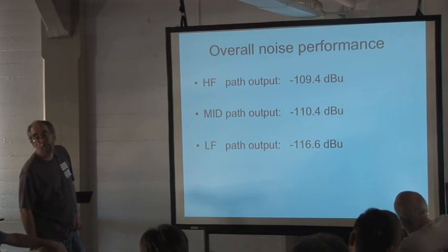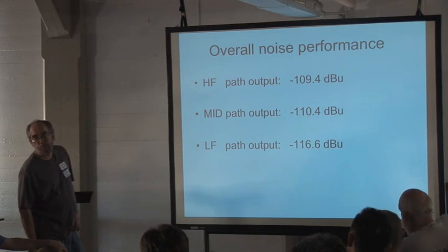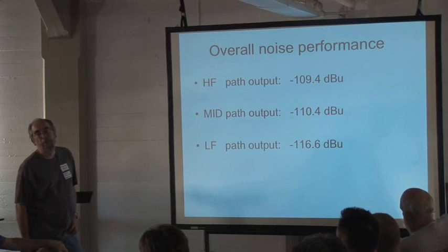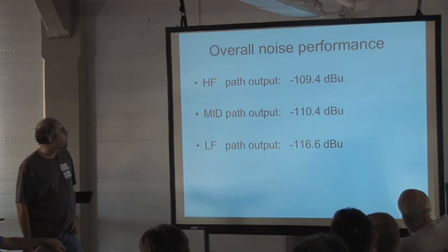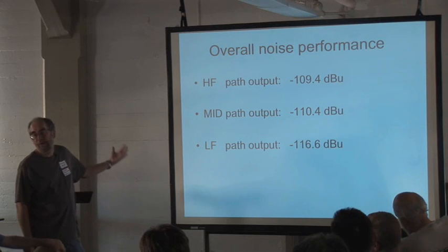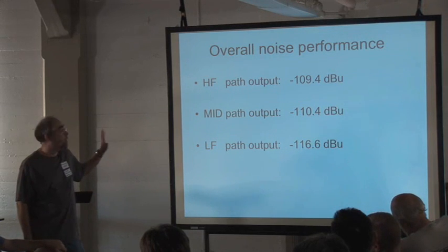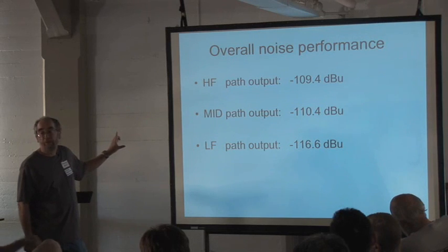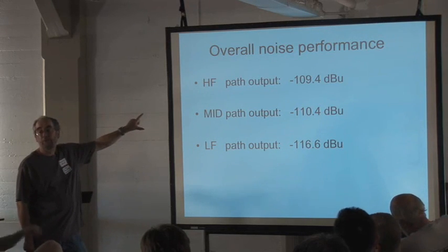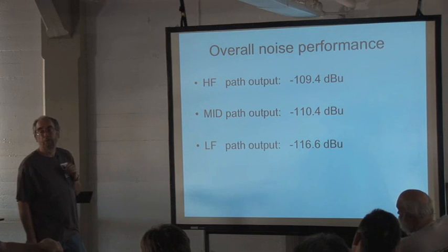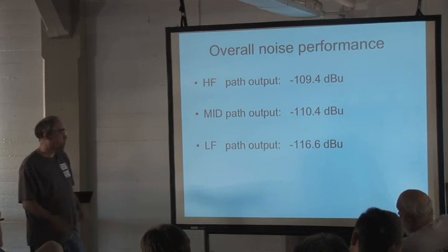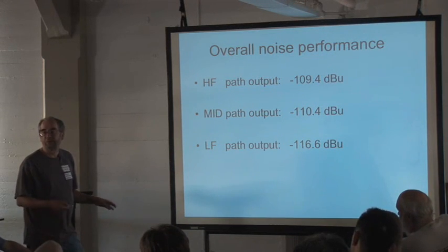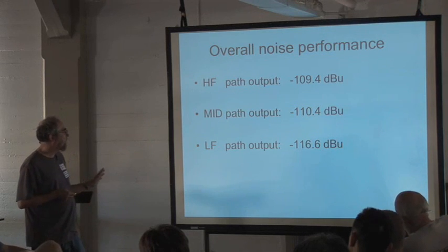Are you choosing a higher output on your low pass filter because of diffraction rolling around and it will equalize it out? No, there is no equalization of drive units or of loudspeaker interaction with the cabinet in there at all. It is just a basic standard fourth order Linkwitz Riley plus the 2 time delay blocks. That is basically all there is to it. It's quite simple. There's no equalization because I don't know what to equalize and what kind of loudspeaker I have got. This is just to show the principle, really.